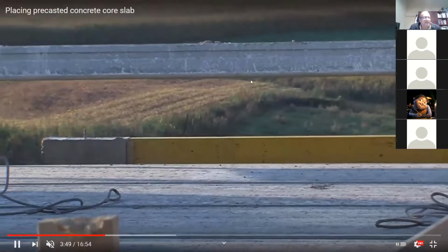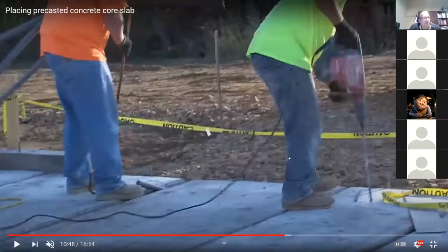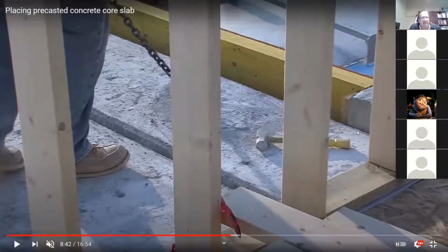So this is actually an excellent solution for a case like that. How are they anchoring those? They're not going to anchor it, just put it in place, and then the concrete topping is going to have some reinforcing. They put the reinforcing in the concrete topping, and this is what we do in precast, pre-stressed parking structures. I'm going to show you lots of details about this, what the reinforcement is going to be, and this kind of stuff. In a case like this it's just heavy, it's going to stay in place, and once you put the concrete topping, it's going to set it in place as the concrete hardens.